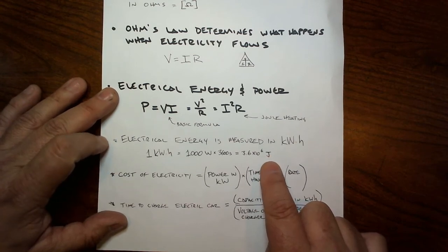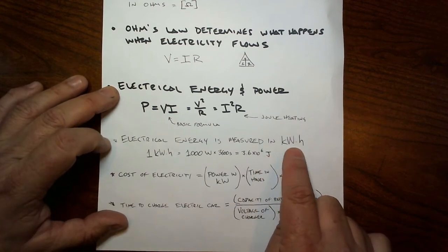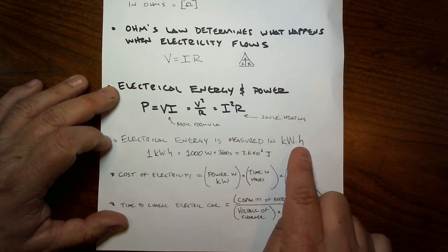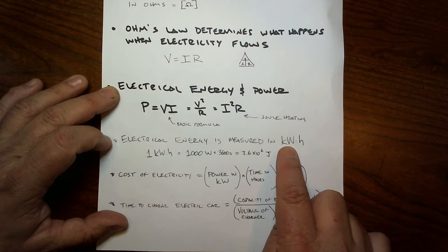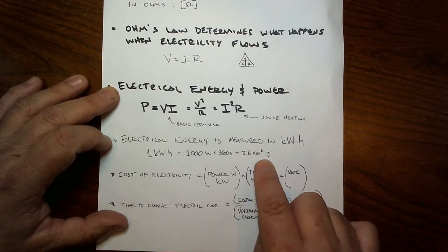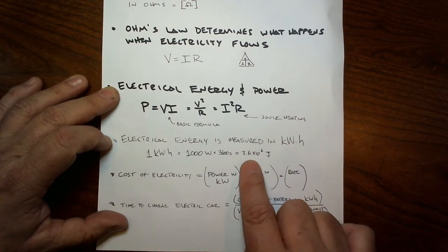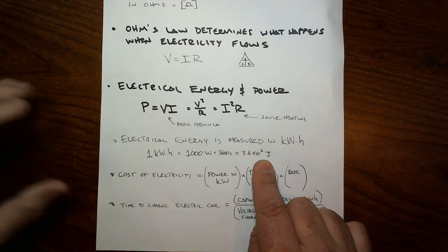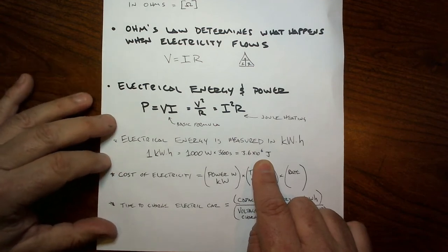So even though this unit that you're paying for from Southern California Edison is a kilowatt hour, it's got watts in it. You'd think it's a power. It's not a power. It's an energy because it's been multiplied by time. So you're really only paying for your energy. Now that's at residential places that you pay for your energy use. They don't care how fast you're using it.